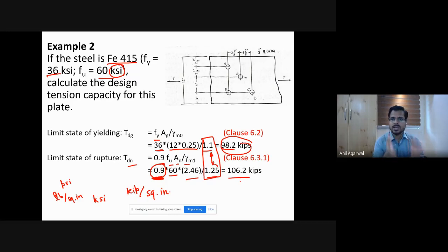But when you actually have a plate and you test it for yielding and for rupture, you will see that yielding, even if it happens at one place first, the next place will strain harden slightly, and then other places will start yielding, so it will spread. So overall, you can say that the entire plate, or entire length or cross section, has yielded, and that is very easily quantifiable.